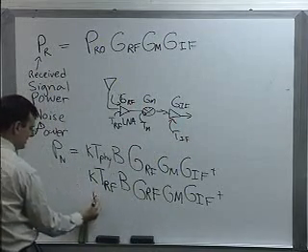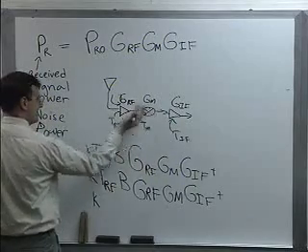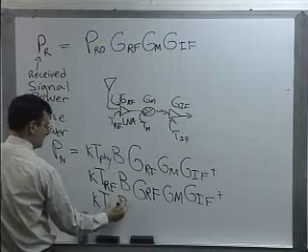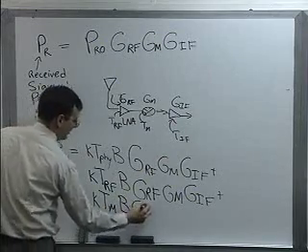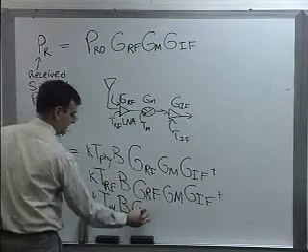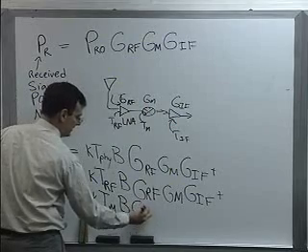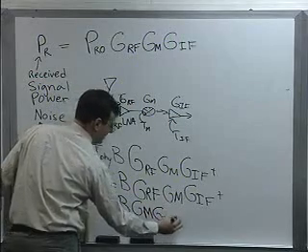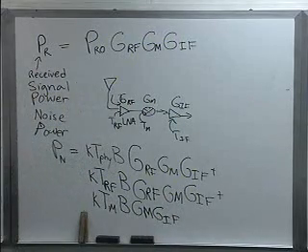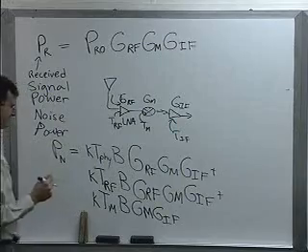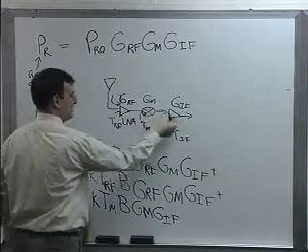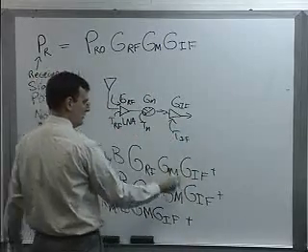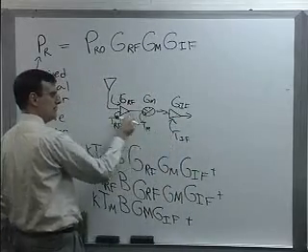And so we can write this as K. The noise that gets added at this point is K, T sub M, times a bandwidth, times not G_RF. It's already past that device. It only experiences the gain of the mixer and the gain of the intermediate frequency amplifier. And then, of course, the last stage, you get to the intermediate frequency amplifier. And that also adds device noise, but this noise has not gone through the same two gains previously.